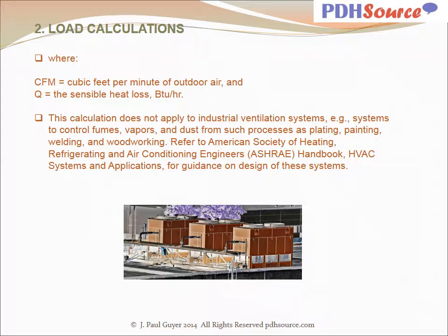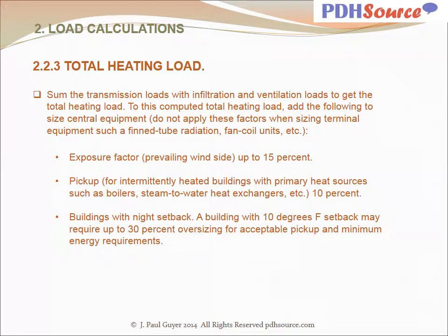Additional information and guidance in this area is available from publications of the American Society of Heating, Refrigerating, and Air Conditioning Engineers, ASHRAE, which is the leading source of technical information in the HVAC area. The total heating load then is the sum of the transmission loads together with the infiltration and ventilation loads.